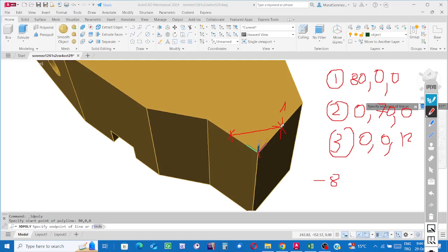But since the displacement is toward the negative side of the x-axis, the positive sense of the axis being in this way, and the displacement from here to there, for having the first boundary of the sketch, is in the negative sense of the x-axis, the abscissa for the second point with respect to the origin is 0, but with respect to the first point is minus 80.